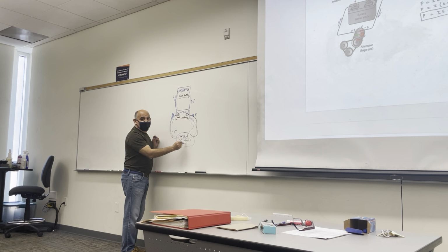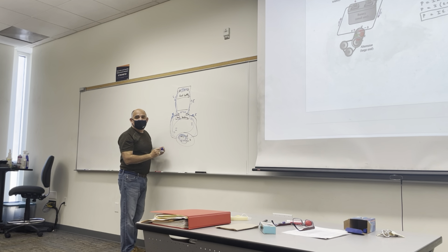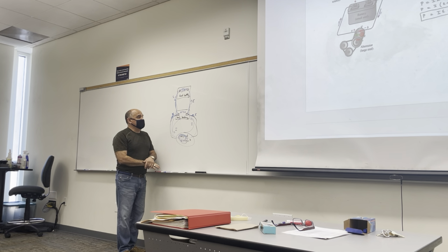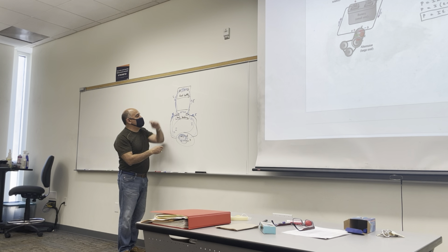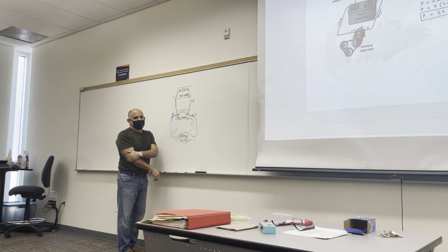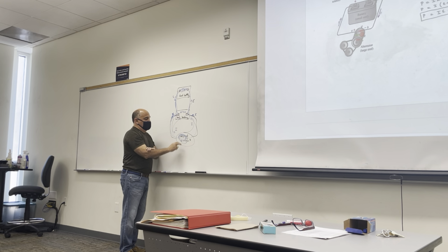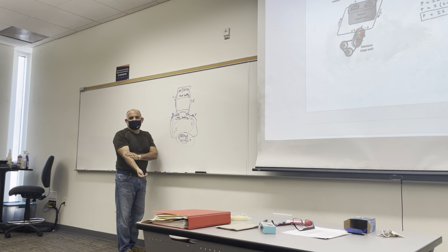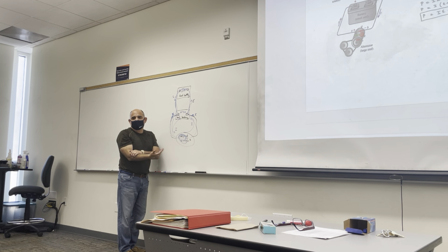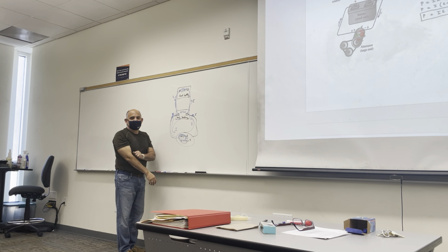And as you get the alternator going, it'll charge your battery in the process. So you should jump start it and let it run, a few minutes, 5 minutes, 10 minutes. Once it's going, you can disconnect this one, and then you can charge this and charge it for like half an hour or something like that, right? The thing is that if the battery is bad, then nothing will happen. Yeah, you'll just use it for a while, and then once you drain it, then you'll have to do this again, or end up buying a new battery, so you don't have to do this each time.